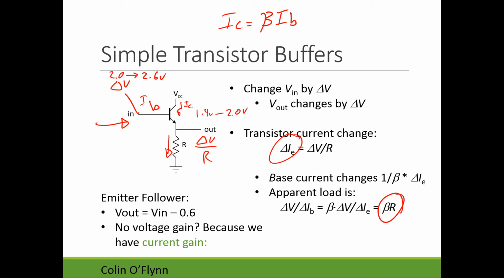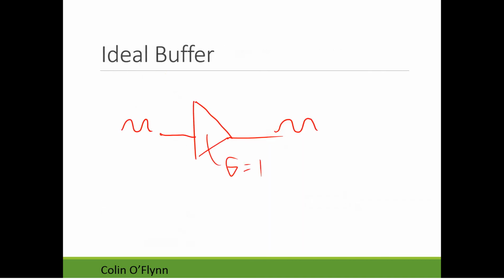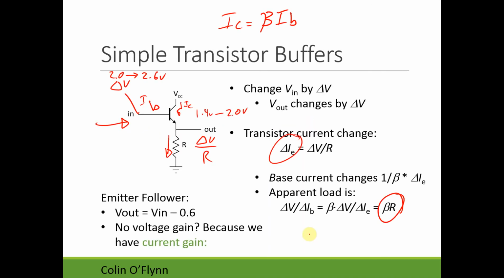So this is, how strongly can we drive a signal? We can make R some smaller value, like 300 ohms or something, even though at the input we have a sensor that has a very large source resistance, and then we're able to drive a stronger signal.